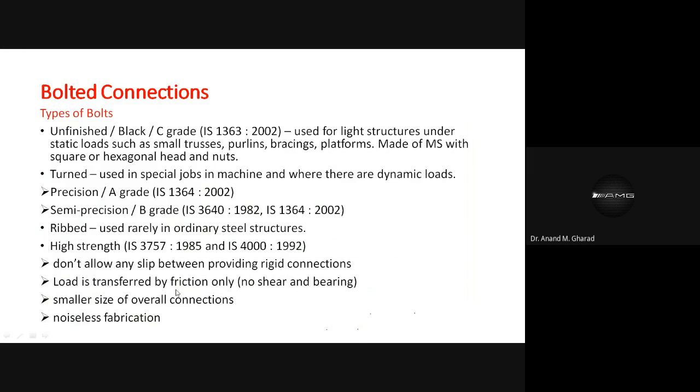So load is transferred by friction only. Shear, you know. Bearing, I have told you. So these two concepts are not considered in case of high strength bolts. Then smaller size of overall connections can be obtained with the help of such type of bolts. देखो इसका मीनिंग क्या है, smaller size of overall connections.